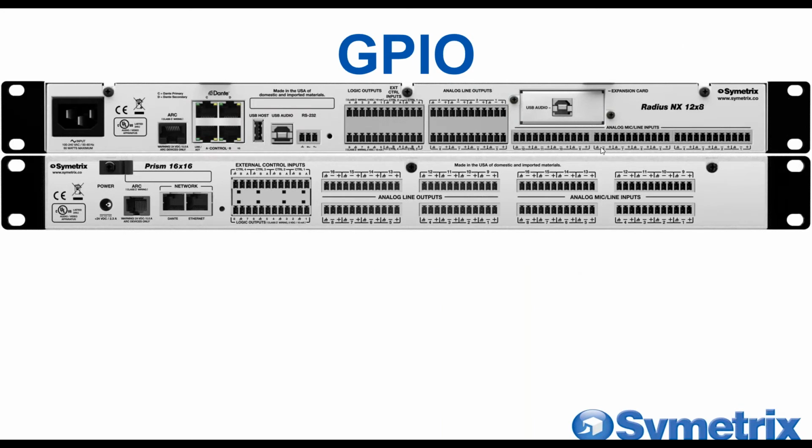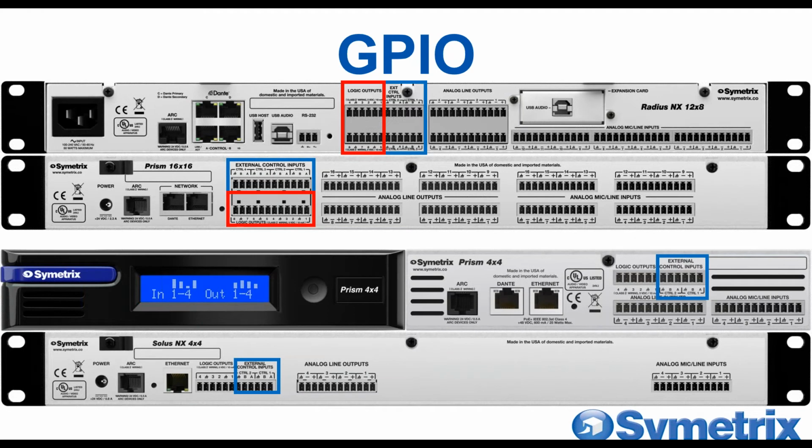So what is GPIO? Put simply, they're open inputs and outputs on the back of the DSP. They're used to interface with other electronic devices. The larger DSPs, such as the Radius NX and the Prism 16 that we have here, all have 8 switch inputs, which are also switchable to 4 potentiometer inputs. That's all done in Composer software, that switching, and 8 logic outputs. DSPs with smaller I/O counts, like Prism 4x4 and the Solus NX 4x4, will have fewer GPIO as well. These ones have 4 switch inputs and 4 logic outputs. So it can vary a bit, but basically they all have some amount of GPIO.